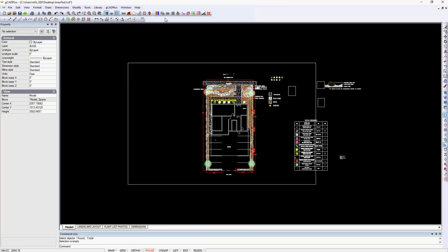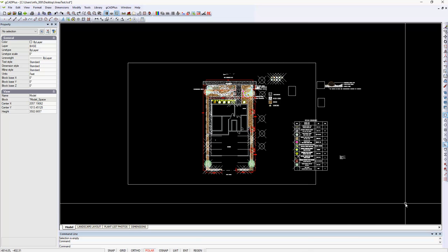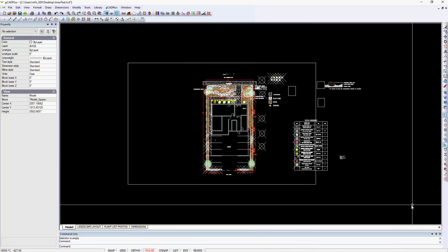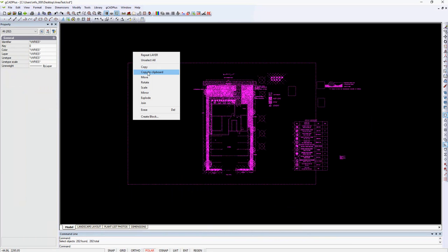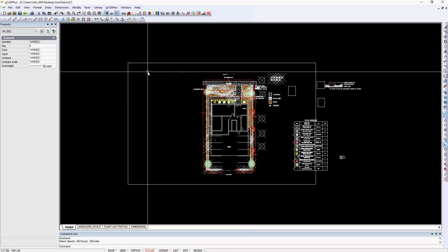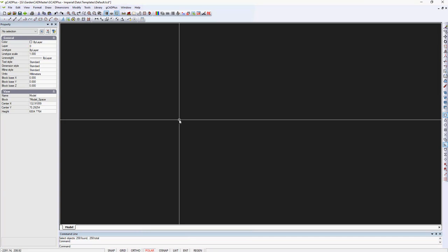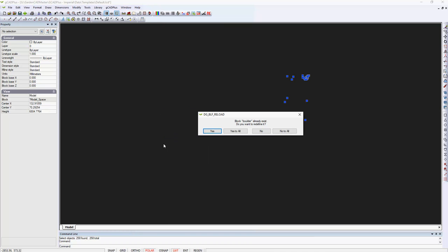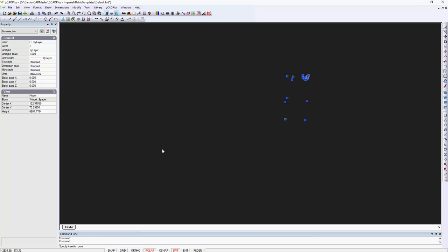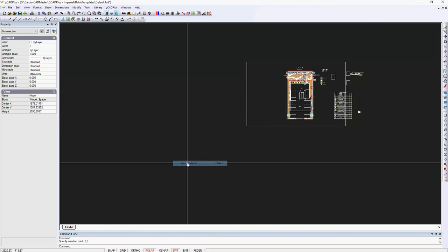So I'll make sure all layers are turned on, even the construction layer, they're all on, and now I can see there's a point marker needs to be adjusted, and I'll select everything and I'll copy it to the clipboard, I think, and then pop it into the default drawing for gCADPlus in the US environment, and then paste that drawing in, say yes to their insertion point, click in there, we'll put it in at 0, 0, and zoom extents.